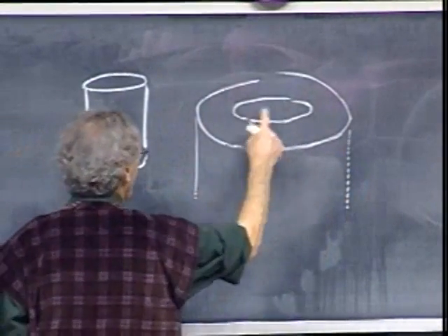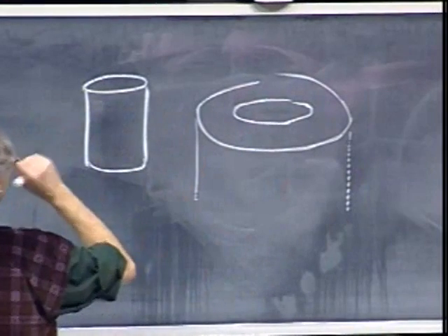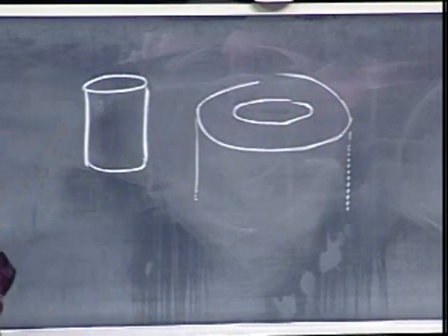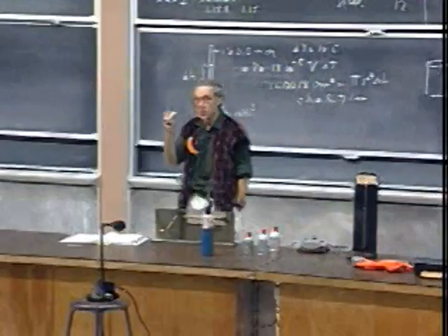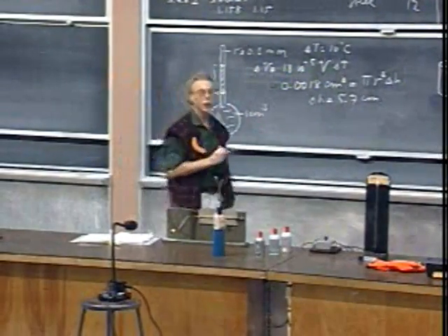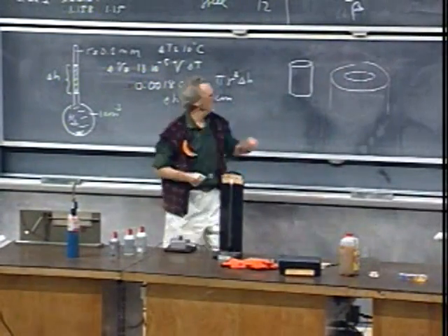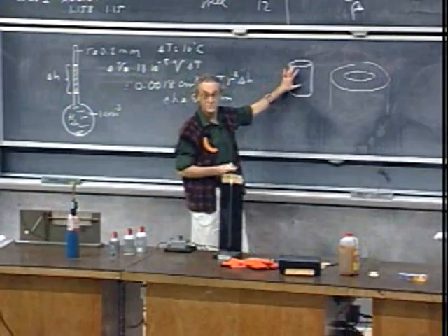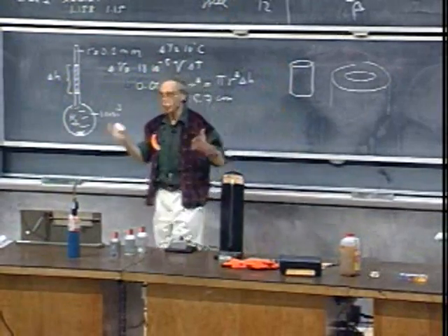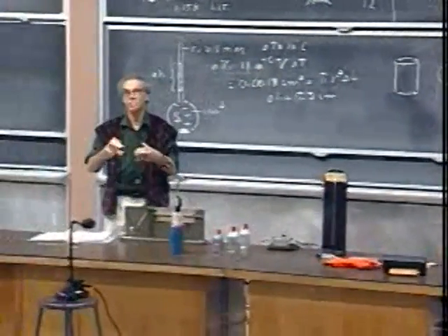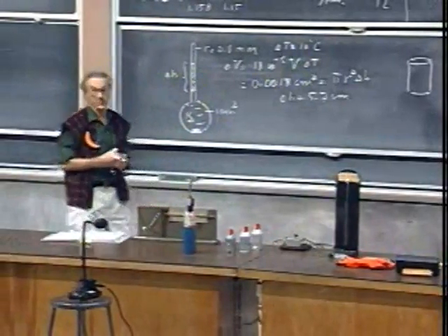Now this opening is smaller than this. Just a little smaller. Purposely made that way. You heat this one, expands, and then you put it over here, it will fit, and then you let it sit, it cools, and it tightens itself up. That's called shrink fitting, a technique which is often used.